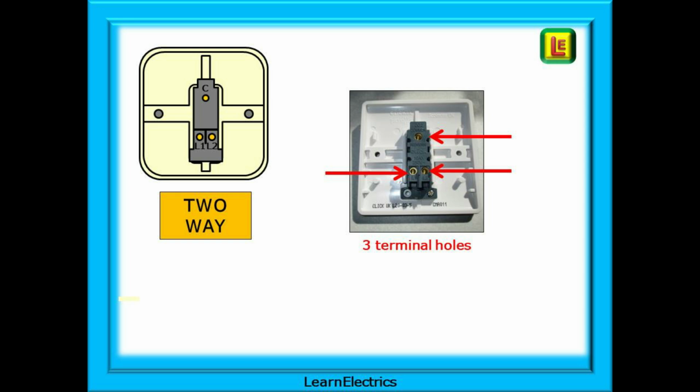These terminals are named common, L1 and L2 on many switches, but manufacturers like to have their own numbering system, as you will find out, and the switch could be labelled L1, L2, L3, where L1 is the common, especially with older switches. In this video, we will stick to the convention of common, L1 and L2.